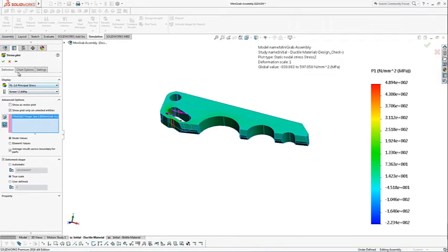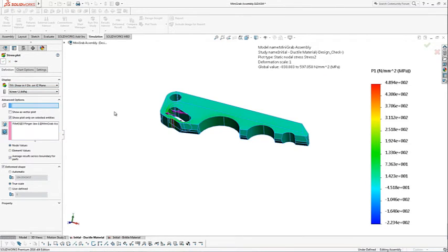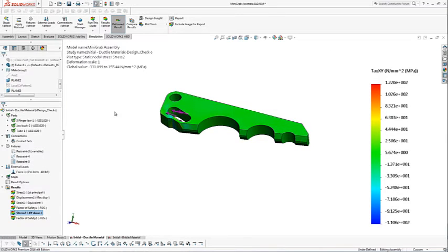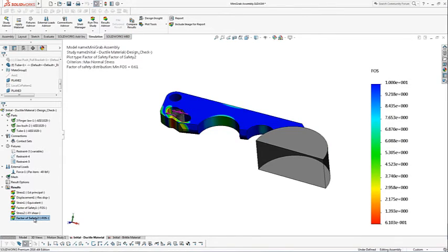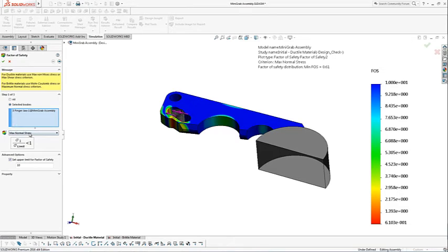But remember, these are not going to be correlated to our principal stresses, right? So I can look at shear on any of the planes, but it's not quite as easy to correlate. If you're looking at maximum normal stress or the von Mises stress criteria, those are easy to correlate in your head, but the maximum shear stress is definitely not, right? So if I come in here and say I want to go to a maximum shear stress, which is also known as the Tresca theory,